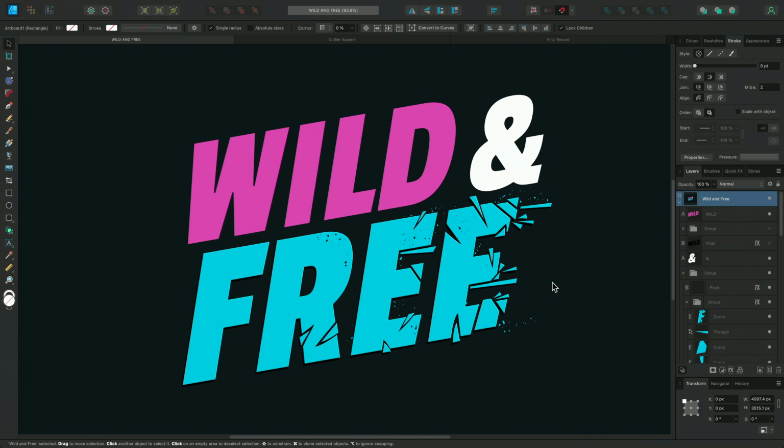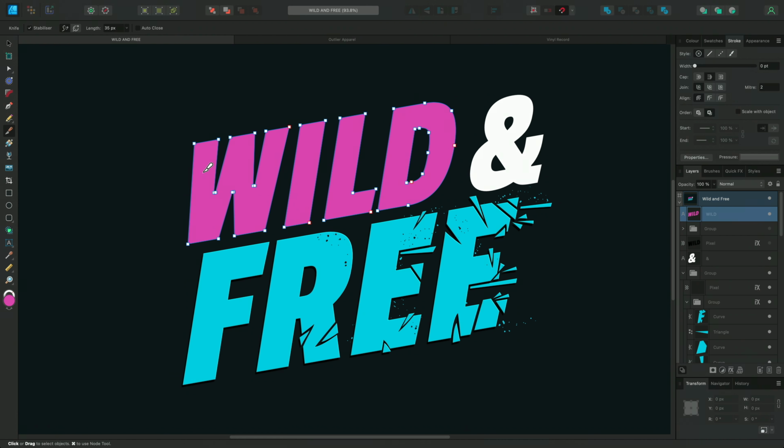So the first thing we need to do is locate the knife tool from our tools panel on the left, or with the keyboard shortcut K. With this tool enabled, we can tap on the vector layer itself to select a particular object, and we can combine that with Shift to make multiple selections too. So if I select this top section of text, we can then take a look at the context toolbar to see the options we have available to us.